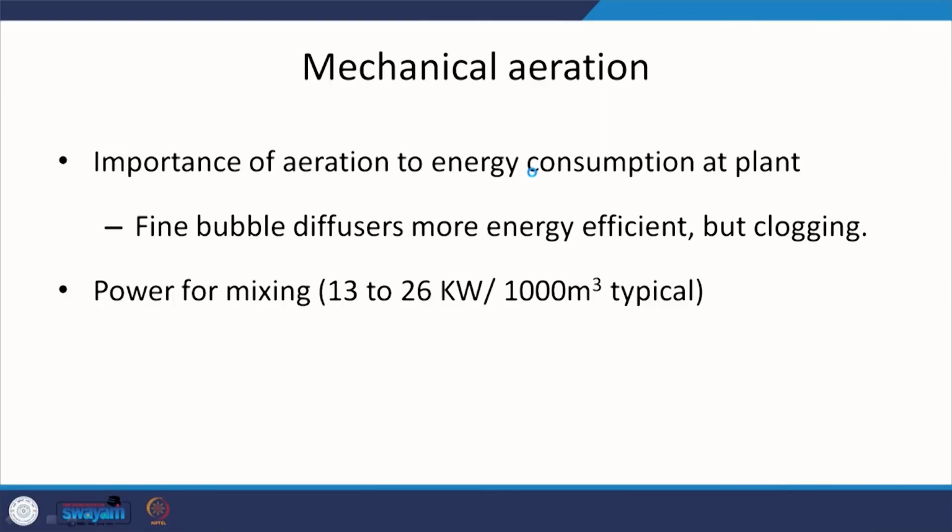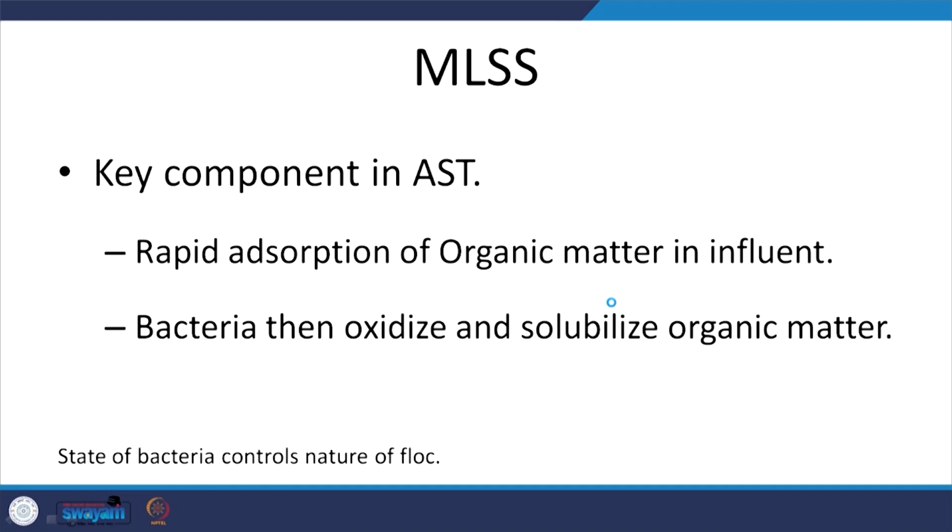So, mechanical aeration, as I mentioned, fine bubble diffusers are more energy efficient, typically with greater oxygen transfer efficiency, but maintenance is an issue due to clogging. Power for mixing, the typical power, you can understand the relevant energy requirements.